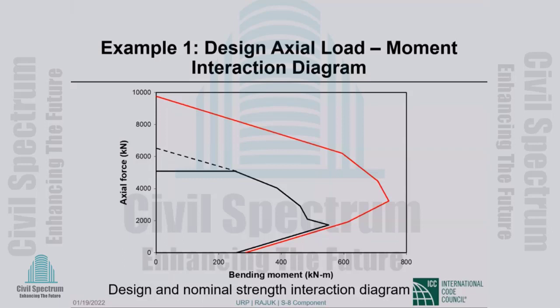What I'm trying to say is that the shortening of this composite column may be different from the shortening of the other columns, particularly after a number of years. The time-dependent part will be different, and that may cause problems. That may have an effect on the floor members that frame into those columns. This should be checked out.